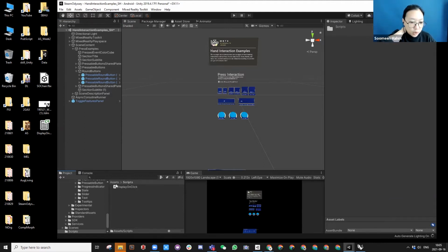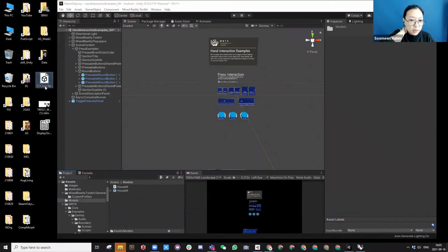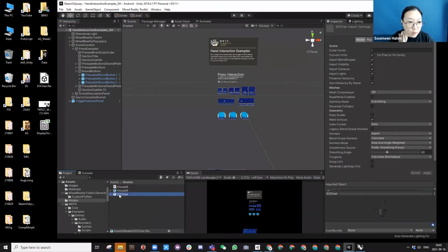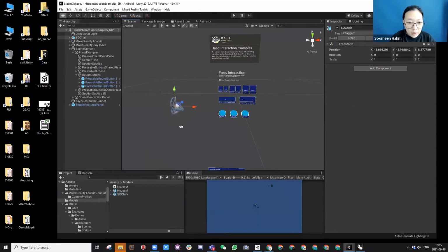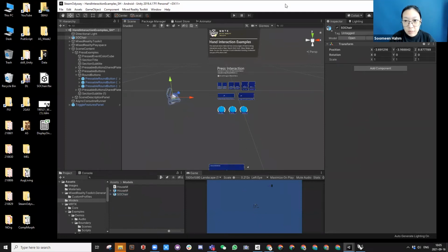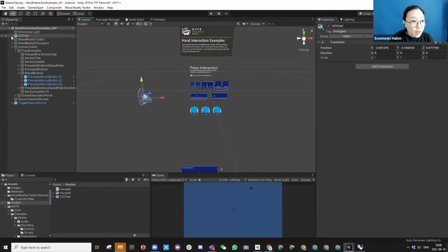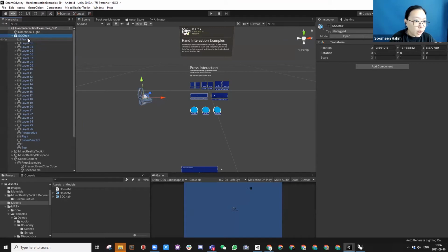In the scripts folder, drag this in. And then we are going to drag our chair model. So in models, the chair FBX model. You drag the FBX model here. When you use an FBX, it comes with all the layer names and the camera somehow. So when you drag this in the scene, you see the camera display became very weird. It's because it has all the Rhino cameras in.